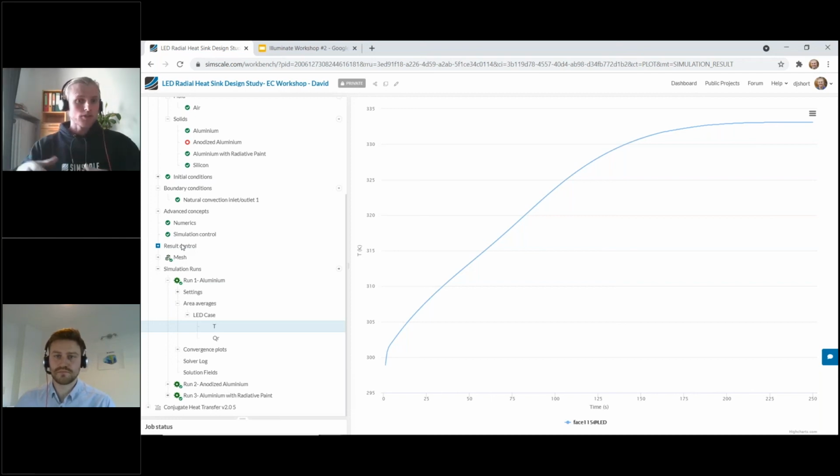to give you confidence that your simulations are converging on a realistic value, not just some numerical growth and reduction in the value. So I like to track my result of interest, namely the LED case temperature. So this is the LED case temperature during the simulation, and we see that by the end it's stabilized onto that final value. So I think that's the most important way to test convergence, is to understand the oscillations and the development of your actual result of interest as well.